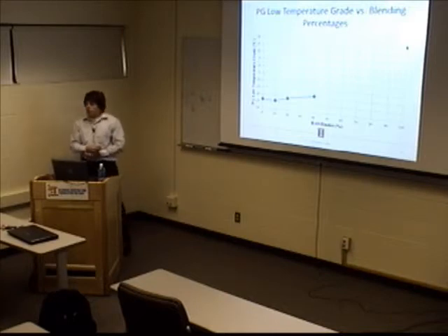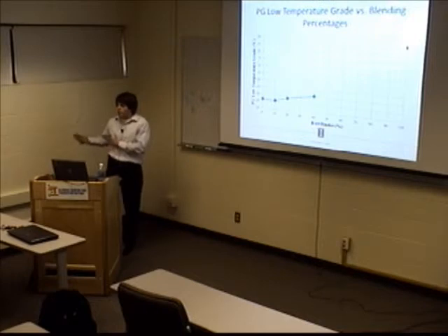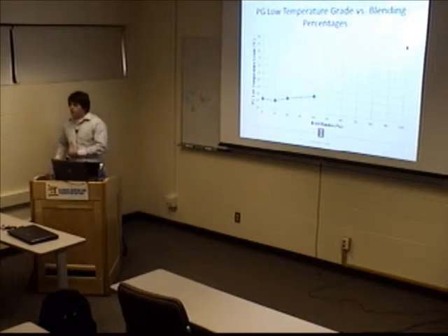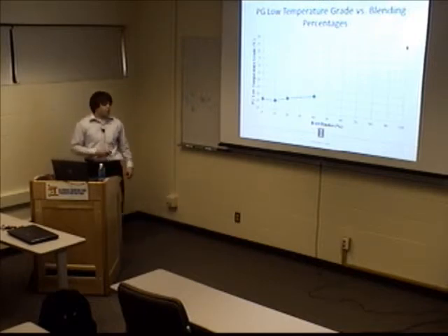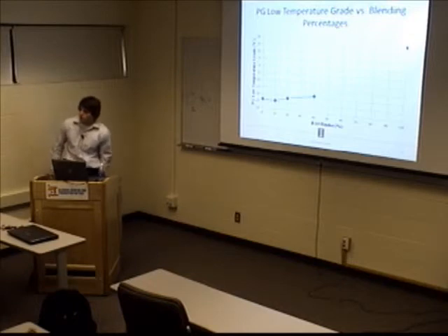I think if you wanted to push the envelope, right now we were just verifying that including that 5 to 10% RAS in a surface mixture will be fine. But if you want to push the envelope, you would need to look at these higher average binder replacements for sure.